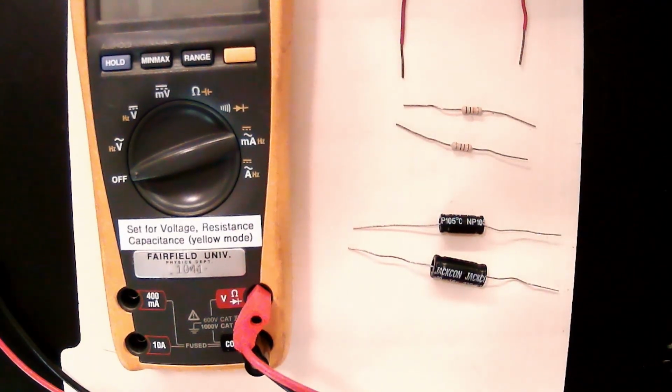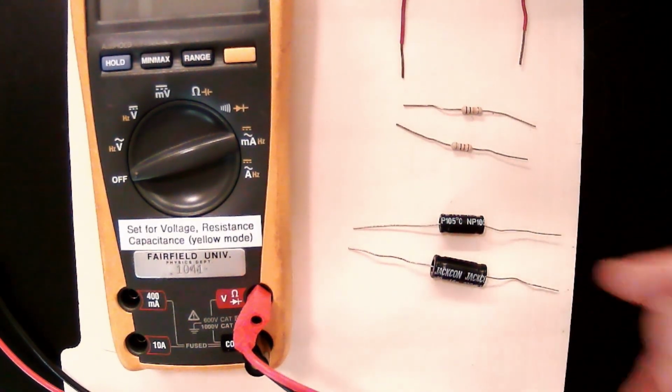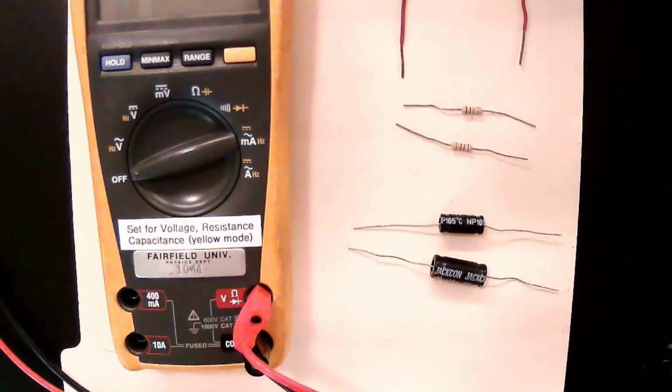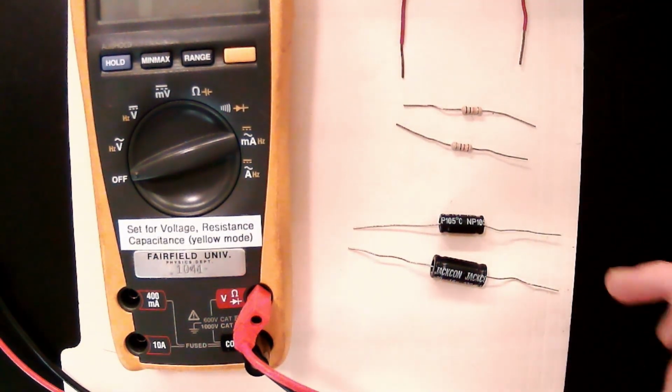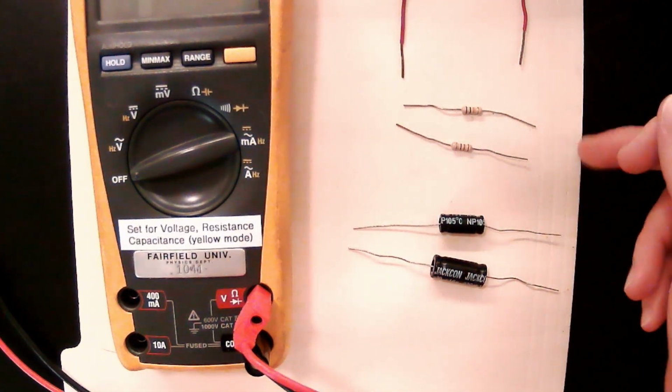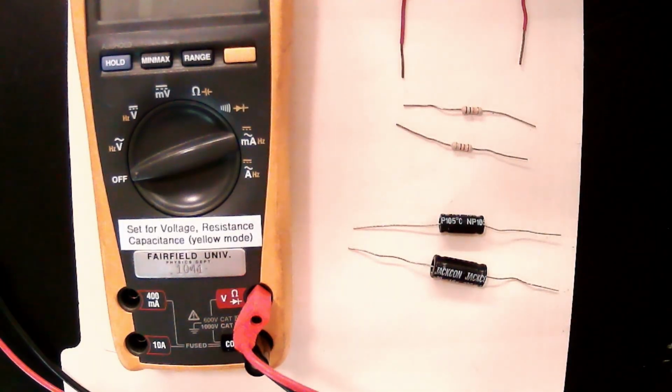All these combinations, essentially saying resistor 1 and capacitor 1, resistor 2 and capacitor 1, are both on the backboard as well as in the experimental procedure section of the lab manual. You'll effectively charge up the capacitors and discharge them through the resistors over some period of time, analyzing the resulting exponential decay of the capacitor's voltage as a function of time to back out the capacitances, right? That's the whole first experiment.